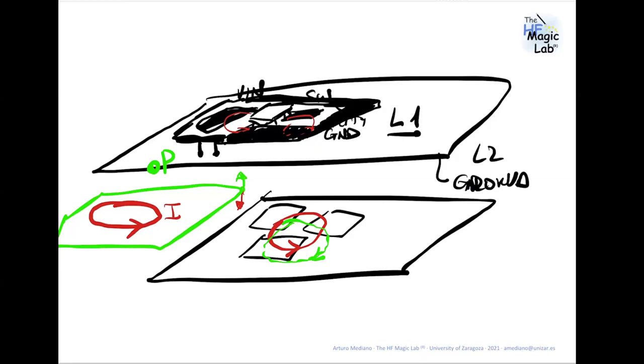Okay. So in this way, multi-layer boards where the second layer is close to the first layer are better than 2-layer boards where the distance between the first and the second layer is 1.6 millimeters or something like that. As close as possible is a good technique, and you will have a quiet system. No?